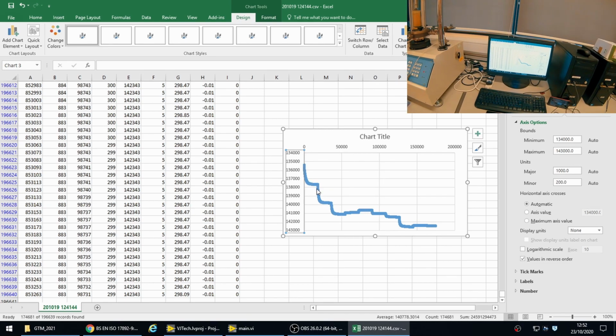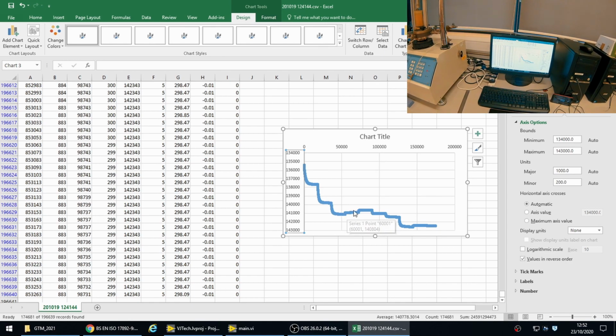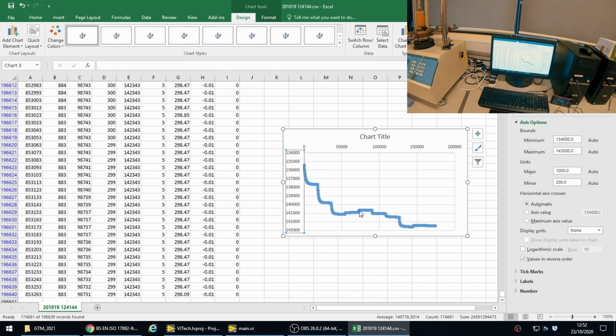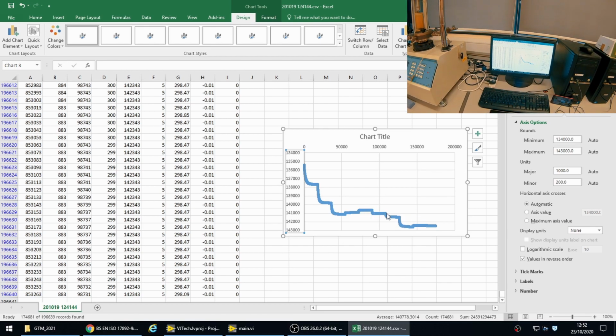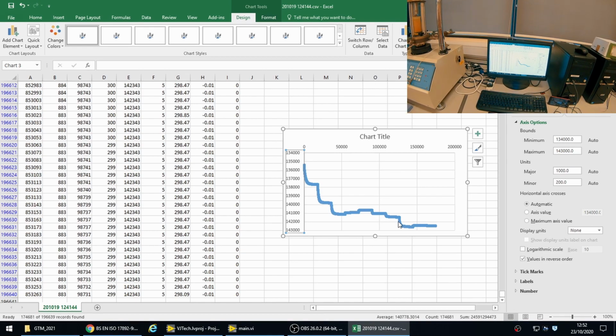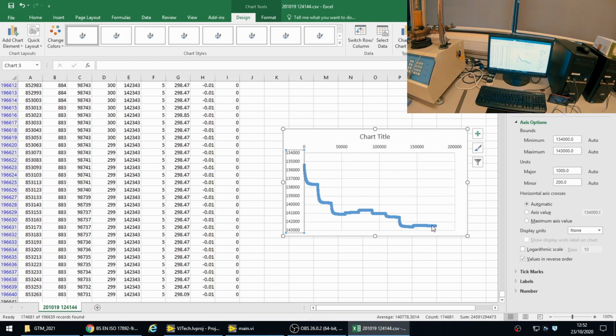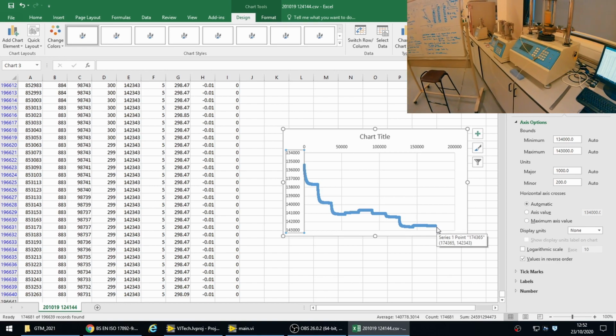We have subsequent decreases along our lambda line, some increases in volume in our kappa line, and subsequent decreases again, and then decreases down our lambda line again, and then a short increase in volume as we get to our final over consolidation ratio.